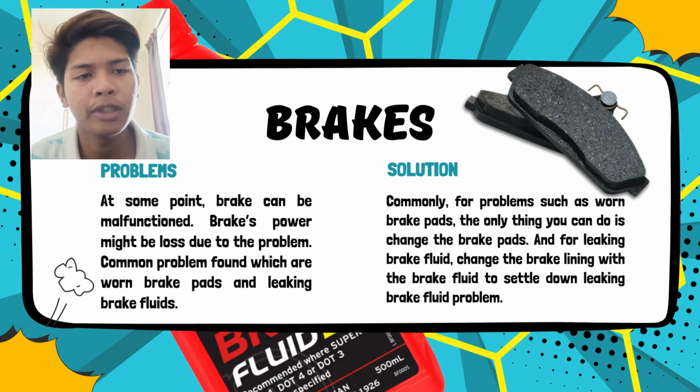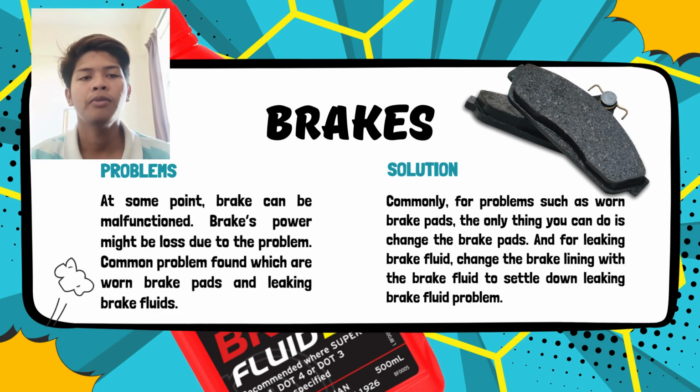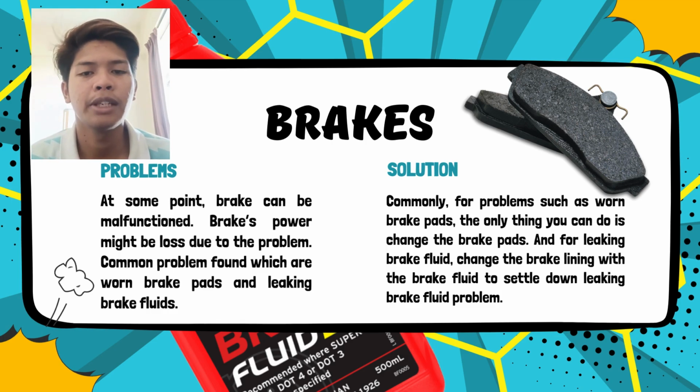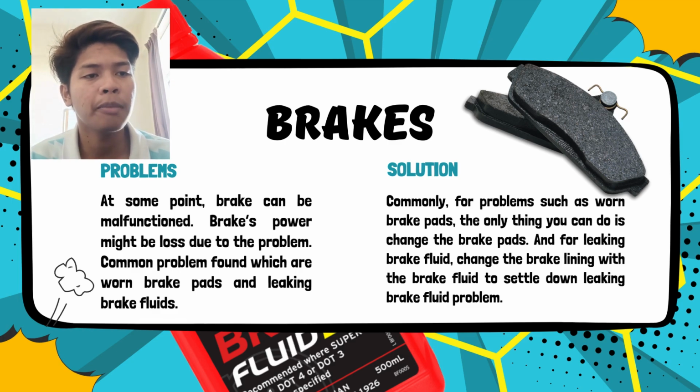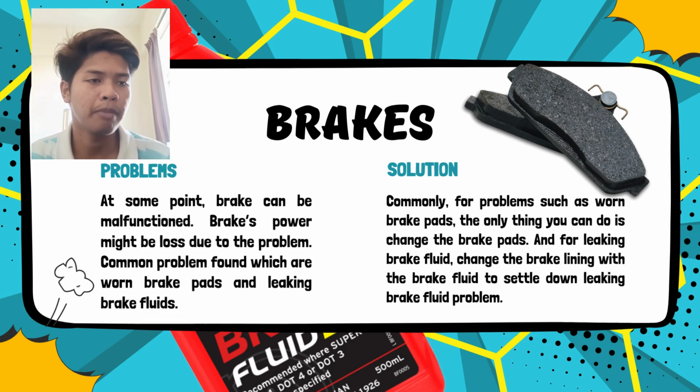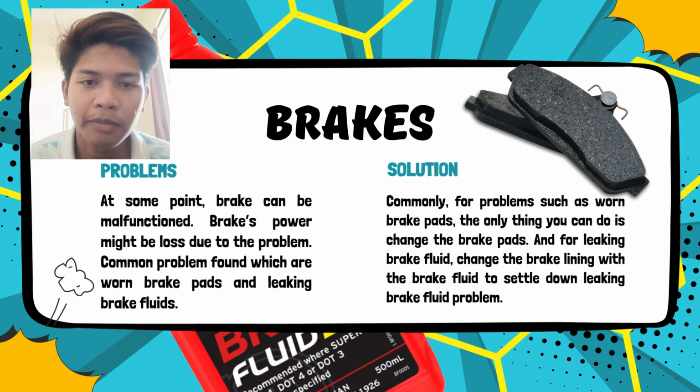Brakes can malfunction. Brake power might be lost due to problems. Common problems found are worn brake pads and leaking brake fluid. And what's the solution? Commonly, for problems such as worn brake pads, the only thing you can do is change the brake pads. And for leaking brake fluid, change the brake lining and the brake fluid to settle the leaking brake fluid problem.